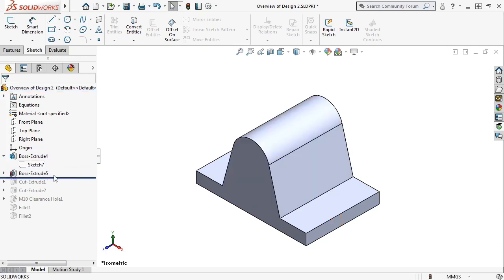Moving on, the tab shape was again created. However, this time, the tab was extruded to the width of the overall part. If I expand this, you can see that the same sketch shape was used, and it was really just the feature itself that was created with a slightly different design intent in mind. Next, an extruded cut was used on a circular sketch just like we saw before, but this time, the hole was cut through the entire width of the part.